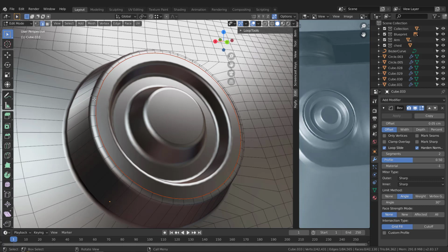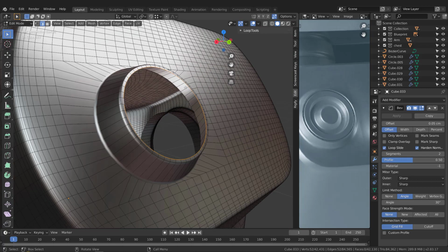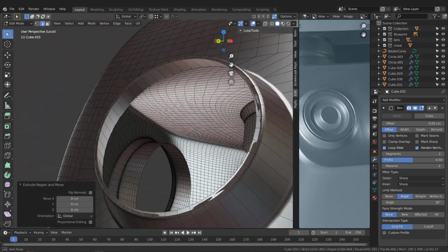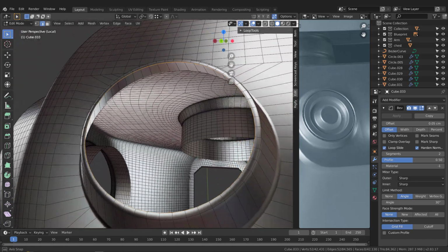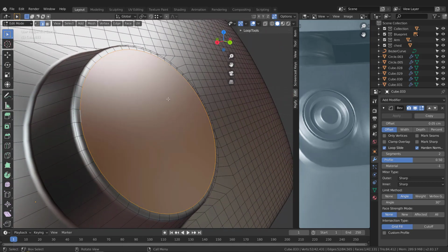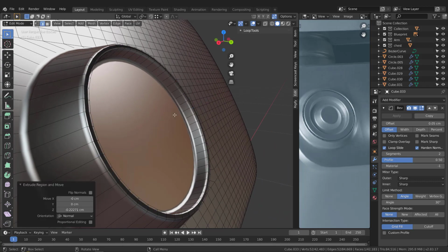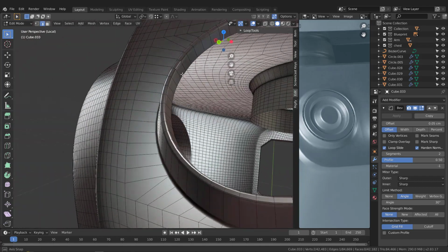Now let's select this edge alone, and let's hit slash to isolate this piece alone, and hit E to extrude it. Let's see, where should we extrude it? Well, we can't extrude it correctly, but we have a trick. If you want, you can hit F to fill this area and hit E to extrude, and extrude it maybe right here, and when you complete, hit X then F to delete this face, and now we have a nice extrusion right here.